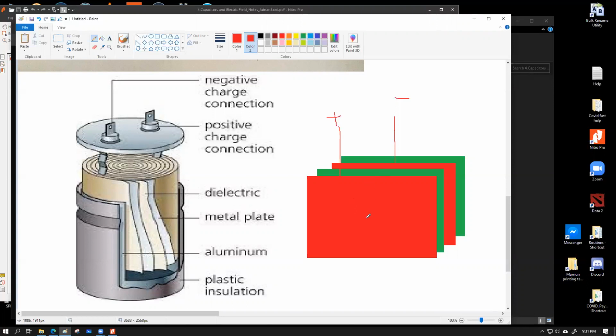By choosing more presence of atoms for this material. For example, if you use cellulose, paper has a certain molecular density. And then if you use some sort of high dense plastic, for example, nylon, that has another polymeric chain structure. So the choice of material will affect how much capacitance you can give, and also the thickness as well.